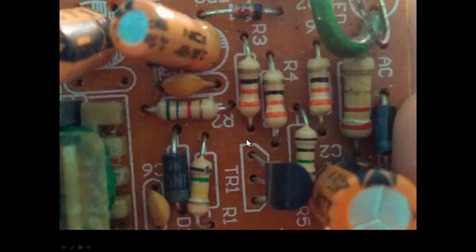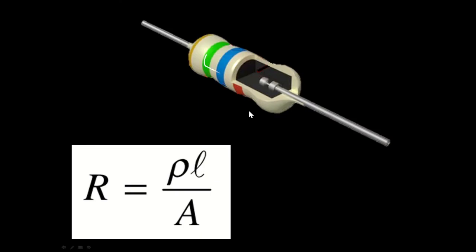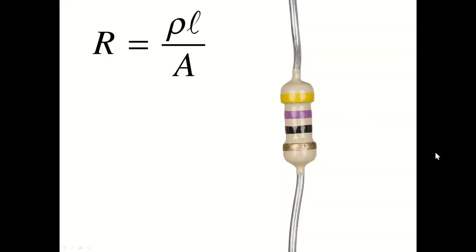All right, we looked at resistance through a wire. Now we're going to look at resistance of these tiny little devices, and they're called resistors. They have color codes on them. So let me talk first of all about what those things are on the inside. Wire comes in, wire stops, new wire goes out, and the ends of those wires are separated by some length. And then inside that, where the electricity flows through, has some cross-sectional area, and it's often made out of carbon, which has a particular resistivity. So the play of those three variables determines how much resistance one of these tiny little resistors has.